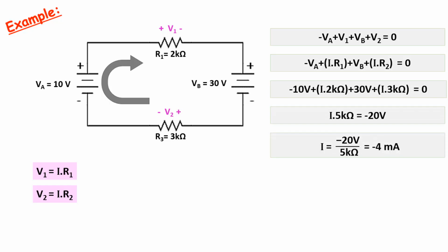We saw that the current was negative coming out. Well, what does it mean? In other words, the direction of the current is actually counterclockwise, not the clockwise we assumed. We have also seen the example that I tried to say at the beginning of the video. We can also rewrite the plus and minus directions of the voltages on the resistors according to this current direction. We found the current in the circuit.